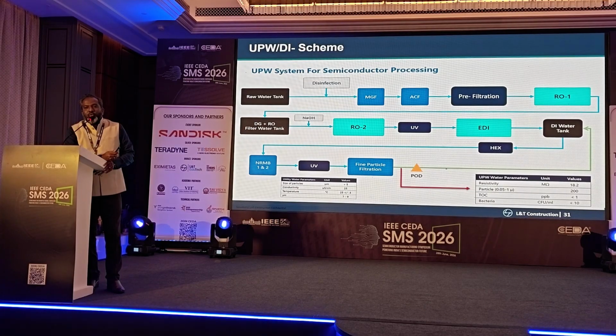And how do you measure whether it is within the allowable TDS or not? There is no way you can measure it directly. The only way to measure is to look at the resistivity of water. So we are talking about greater than 18.2 megaohms. The water is not going to have any conductivity, because the impurity in water is actually what leads to the electric conductivity of water. So based on resistivity is what they check: okay, this is fine to get inside.